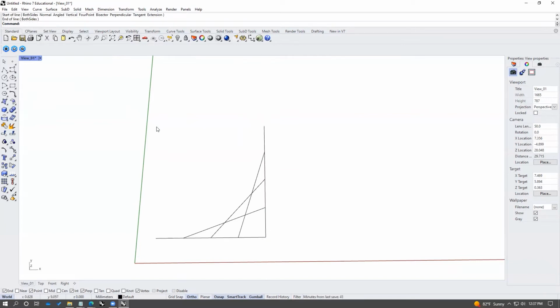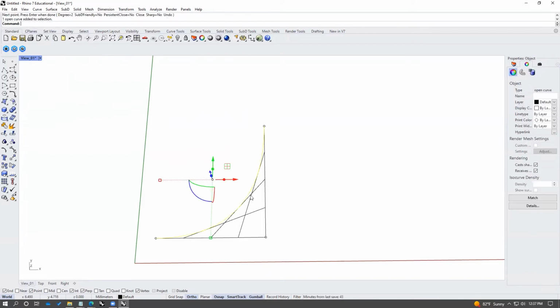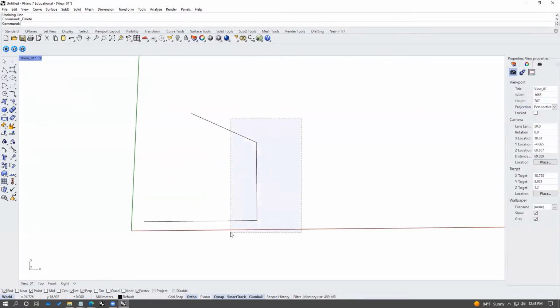Now, if we type curve and then change this degree to 2, we can then left click on each of the control points, and we can see that what we first drew was the tangential lines that define this degree 2 Bezier curve. Now, for a degree 3 Bezier, it's going to be the same process, but we're going to repeat it recursively. So in this case, 2 times.